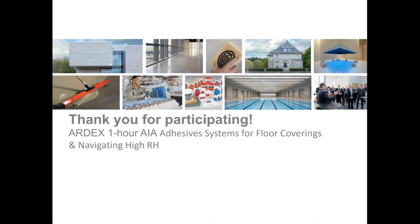So if a topical silicate has been applied, certainly check with your adhesive and flooring manufacturers and get their recommendations. Another good thing to do, just to be safe, is test areas. As a manufacturer, we are always an advocate of test areas, just to see how things are going to perform in that specific environment, especially when things might be a little different or you have a different product used in the equation. Hopefully that was helpful.